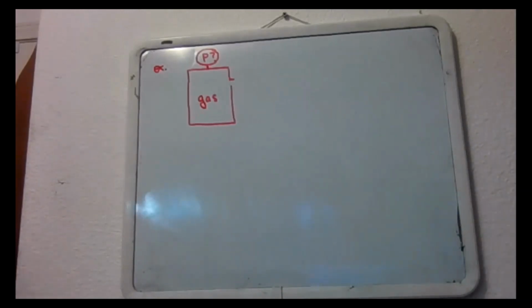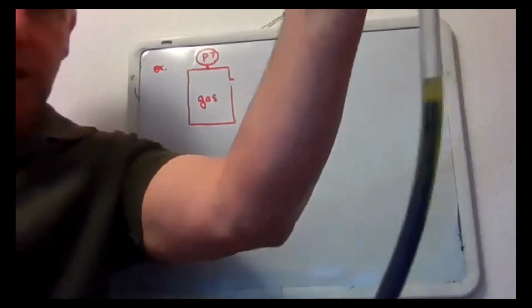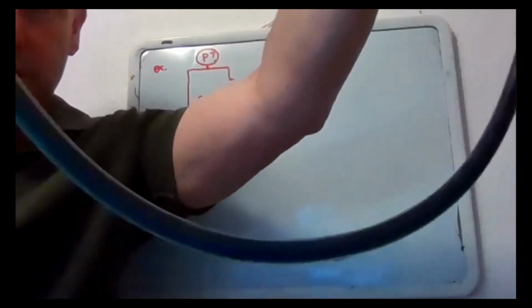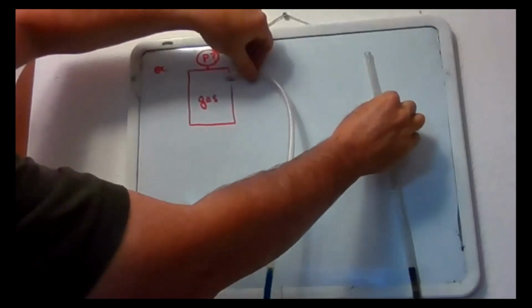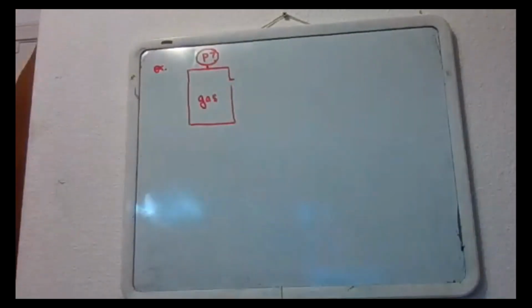But historically, a lot of times these sort of U-tubes were used, and they're still in use a lot of times because they can get what's called differential pressure. I don't know if you can see, I still have a little bit of olive oil in there from something I did earlier, so there's a little bit of separation there with olive oil above the water. The blue fluid is just water with a little food dye in it. There are situations where U-tubes are hooked up like this to tanks, and they can be used to read the pressure in the tank. It certainly is a doable thing. I'm sorry, my arm's in the way. There are physical situations where these U-tubes are still used. We'll do an example where we're trying to get the pressure in the tank using the U-tube.